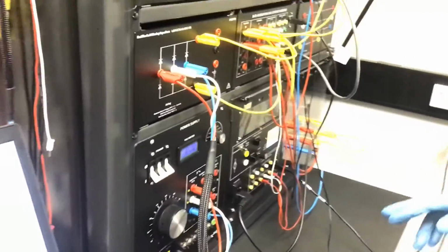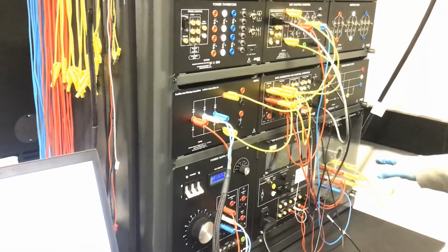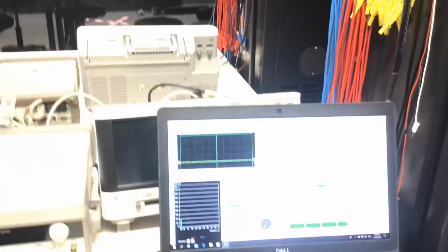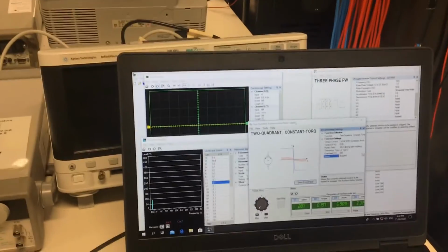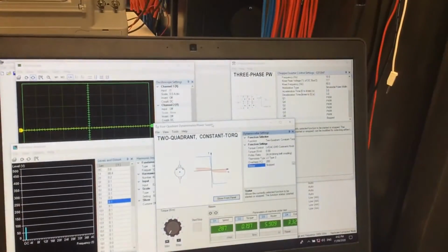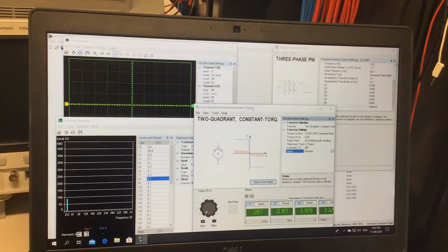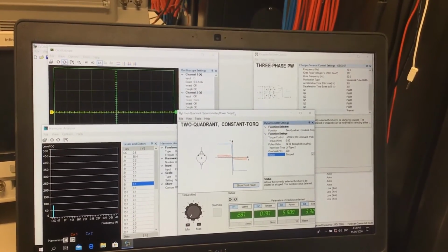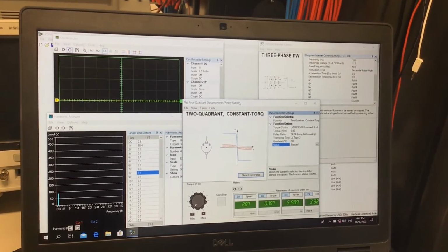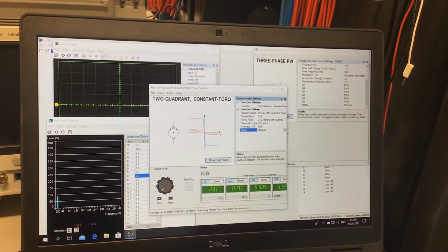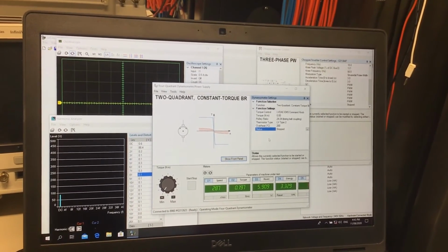Okay, so for this purpose, the wiring is exactly the same as what we have done earlier, but in the setting for the previous exercise, we had not turned on the constant torque brake. In this case, because we need to study the effect of changing the frequency on the torque as well, we need to run the constant torque brake on the dynamometer setting as well.